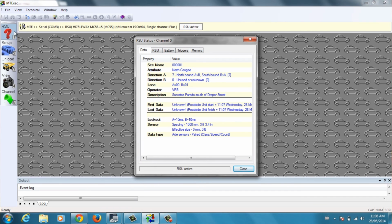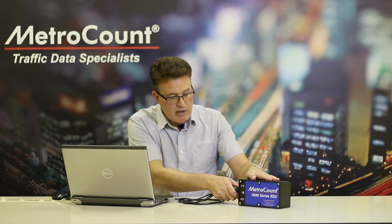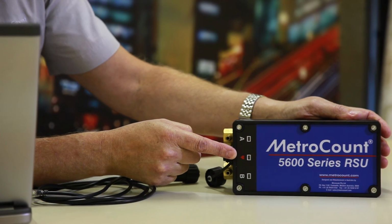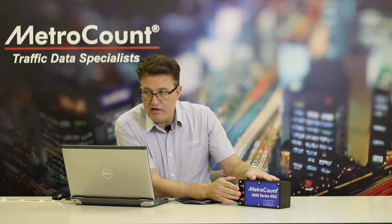Now here we are, here's the status screen again. Site name, site number 1, North Coogee, Socrates Parade, south of Draper Street. That's the information we've entered into the logger. So this logger is now operational. And if I unplug the comms lead, you'll see that the heart LED is flashing once a second. That tells us that the logger is functioning and gathering data.